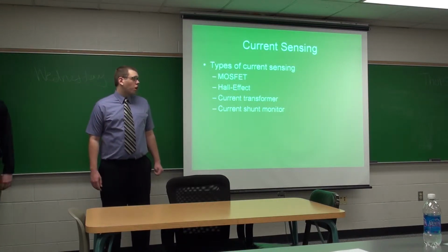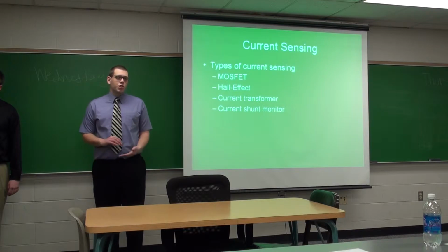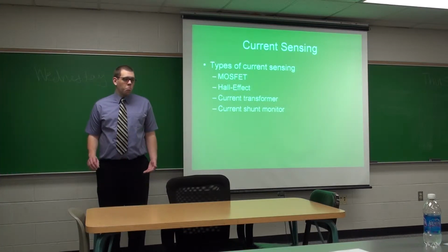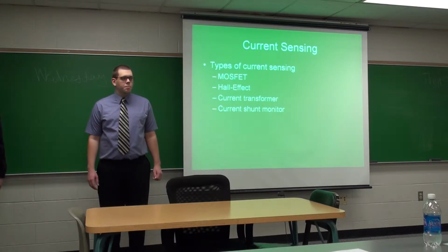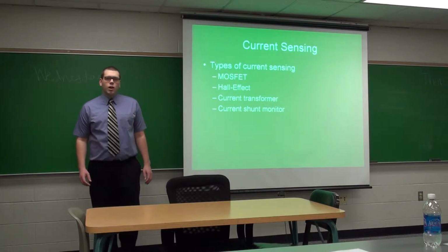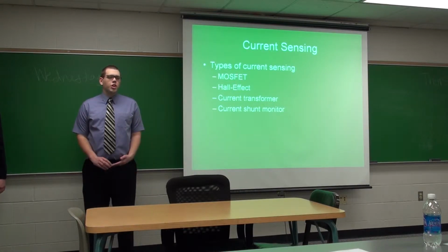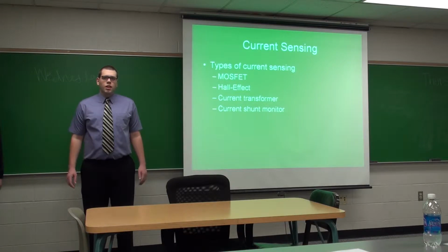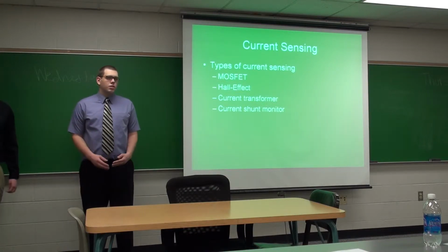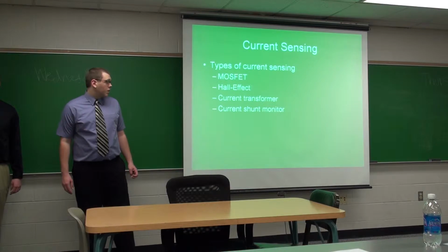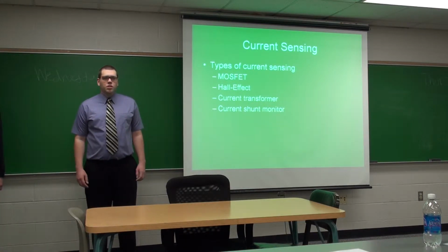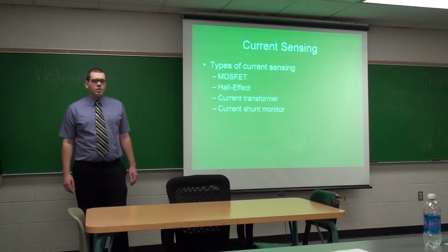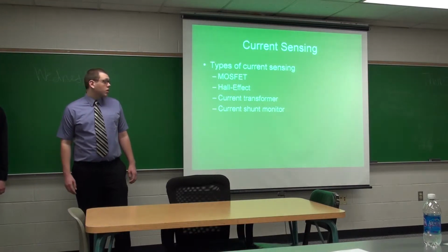We looked into Hall effect current sensing, in which when you push current down a trace on a PCB, a magnetic field is created, and you could view the magnetic field through a toroid. You could then find out what the current is going through the circuit and determine if you need to stop the current from there. For this, the disadvantage was that the toroid would take up too much space on the PCB, and it would be too costly for us.